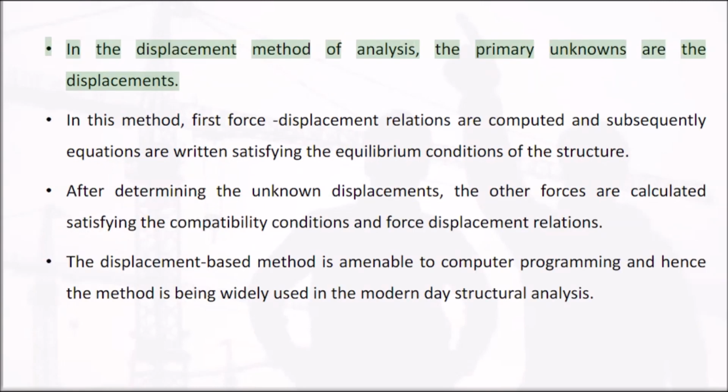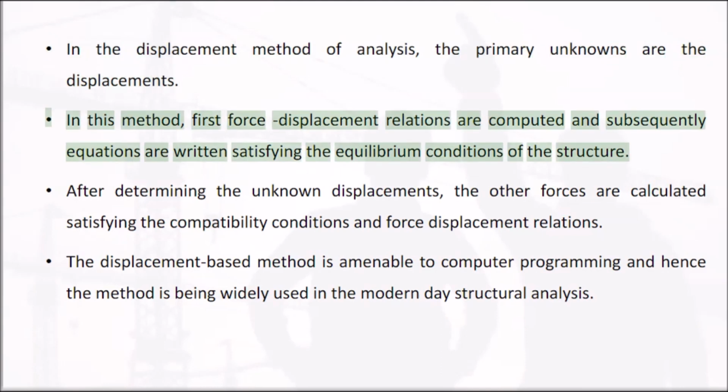In the displacement method of analysis, the primary unknowns are the displacements. In this method, first force displacement relations are computed and subsequently equations are written satisfying the equilibrium conditions of the structure.